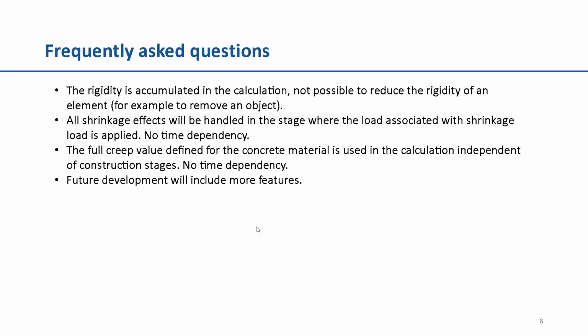Other frequently asked questions is that all shrinkage effects will be handled in the stage where the load associated with shrinkage load is applied. So there is no time dependency at the moment in the calculation. This also applies to the creep value. So the full creep value defined for the concrete material is used in the calculation independent of the construction stage. So no time dependency.